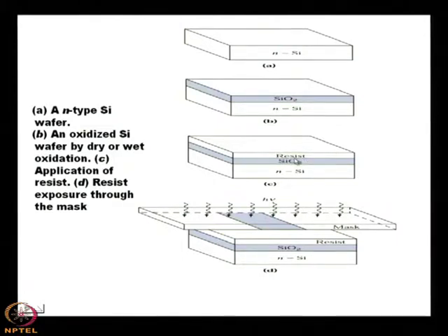You see that here we have written that photoresist must be coated on the SiO2 surface. So first you take the substrate, you make the oxidation on the surface, and above the oxide surface you coat it using some photoresist.